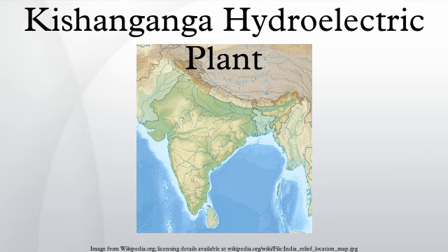Design. The project includes a 37 m tall concrete face rock-fill dam which will divert a portion of the Kishanganga River south through a 24 km tunnel. The tunnel is received by a surge chamber before sending water to the underground powerhouse, which contains 3x 110 MW Pelton turbine generators. After the power plant, water is discharged through a tail race channel into Woola Lake. The drop in elevation from the dam to the power station will afford a hydraulic head of 697 m. This problem is taken up by BHEL.